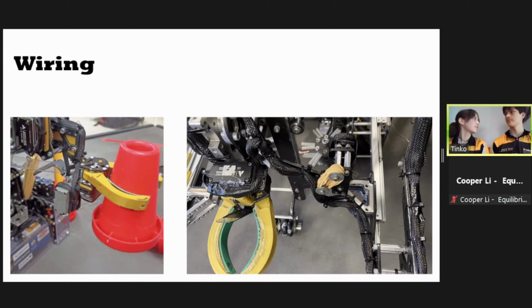There are a couple of things to take note of that are really important when you're doing wiring. The first is to avoid as many kinks in your wire as possible. Always try to do turns or slight bends rather than twists. As you can see in this image on our intake, we have a lot of degrees of freedom, but the wire doesn't bend fully flat. The furthest the wire bends is about this much, so that there's no stress on the wire inside.